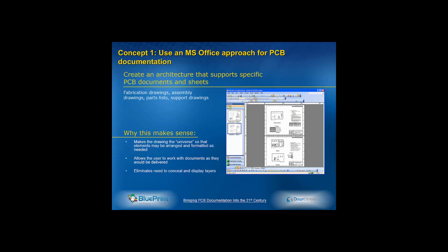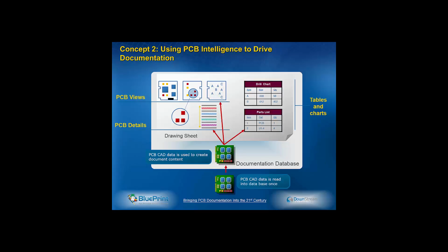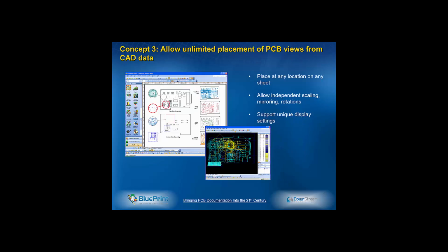First of all, we wanted to use a what you see is what you get type interface. We no longer want to hide or combine layers to get the final document. We wanted to use the PCB CAD database to drive the documentation, since a lot of the work is done already for you if you're able to use that PCB design database.